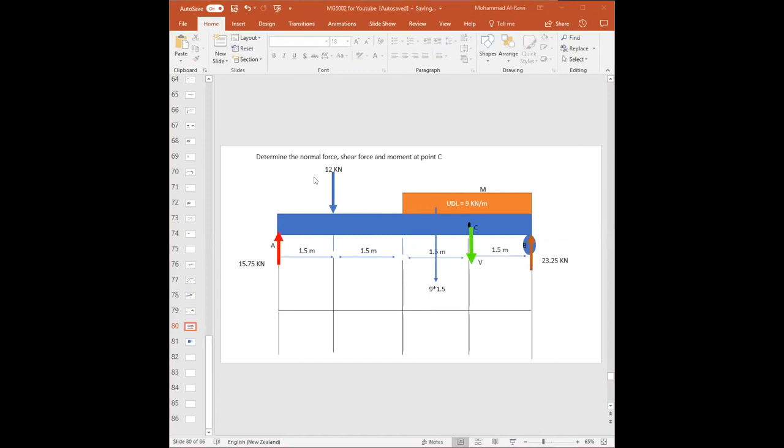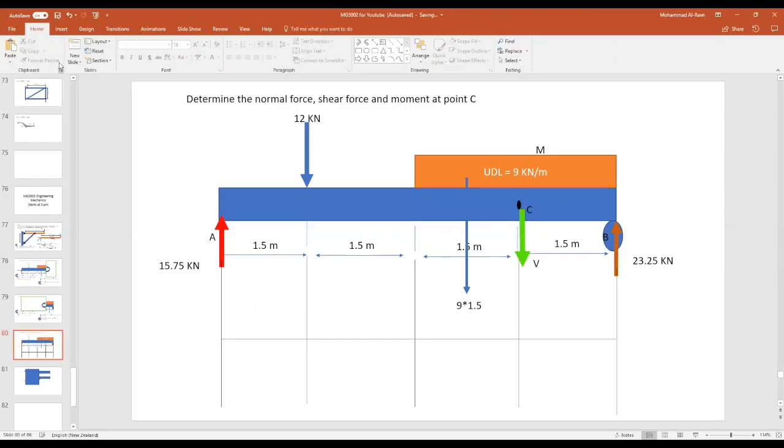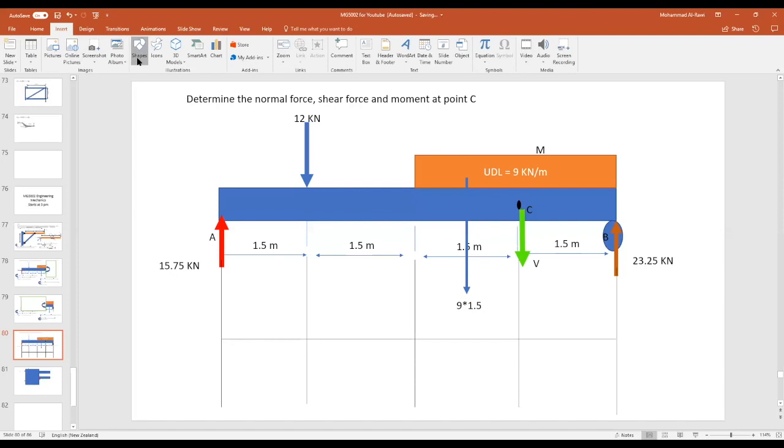All right. Now, what we learned for the shear force diagram: always we start with one of the free ends. I prefer to start from the left, except for the cantilever. What we say is you start from the free end. Okay, so that's something really very helpful for you guys. So I'm going upwards with a value.